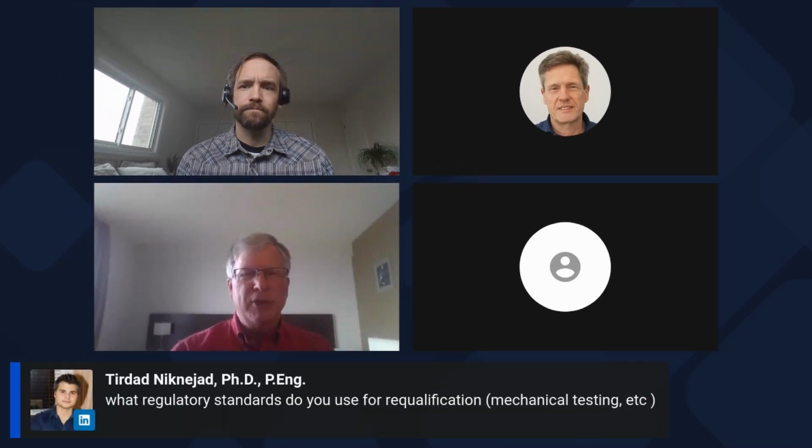I guess we should keep in mind that rejuvenation is alloy specific, not shape of the blade specific. And different manufacturers may use the same alloy, which means that the same rejuvenation recipe, if you want to call it that, will work regardless of the size and shape of the blade or vane component.